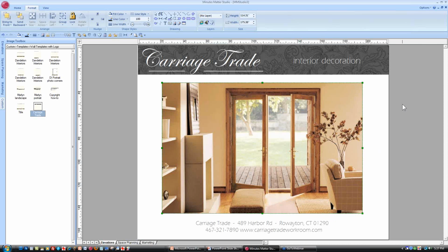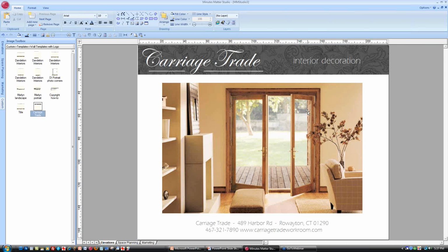The most important thing to do now is to change the drawing scale. We are working in the 1 inch equals 20, but that may not work for this particular photo. And we need to make sure that we've changed the drawing scale so that the images we drag on are to scale, and also that the fabric is the correct representation. You don't want to show the client a very large print on your rendering and have it end up being a smaller print when it's installed.